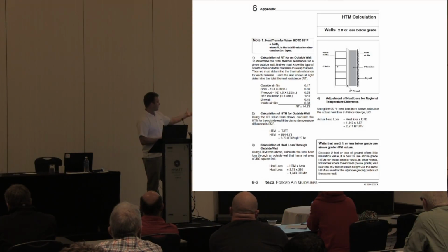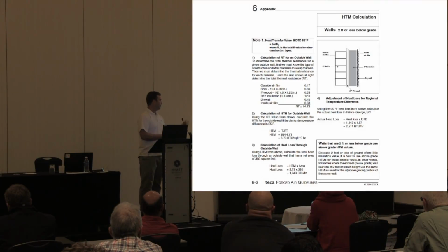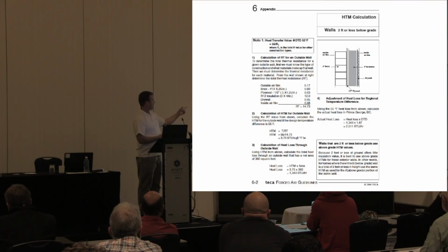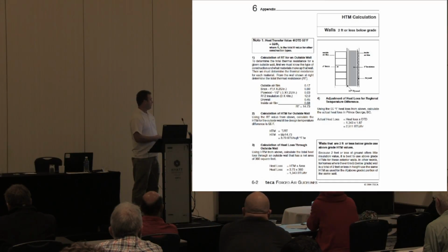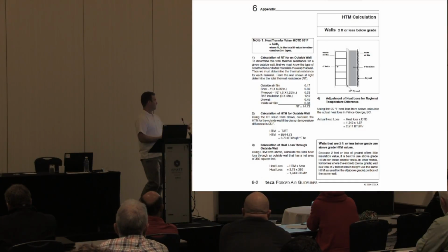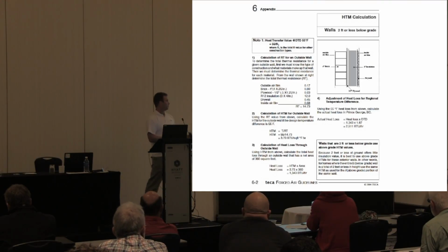And then in this case, it's a 2x4 wall, so it's only R12. So we have 3 times 4 per inch, which is 12. And then we have drywall, which is 0.45, and then we have the inside air film, which is 0.68. So basically what we do with this information now is we go through and then we do it by the temperature, and then it gives us the calculation to put into the factor per square foot per degree Fahrenheit.